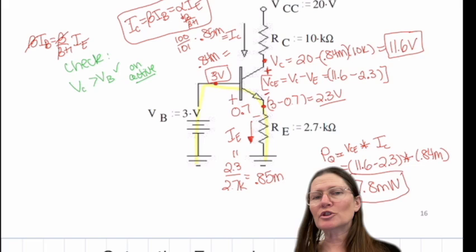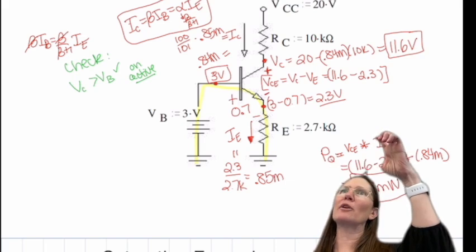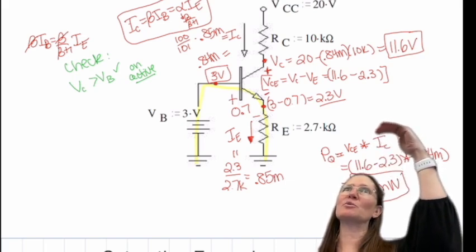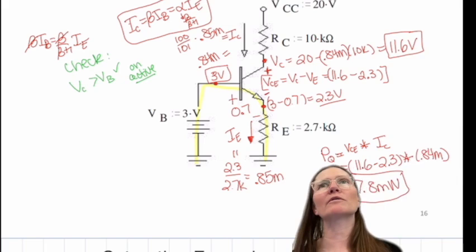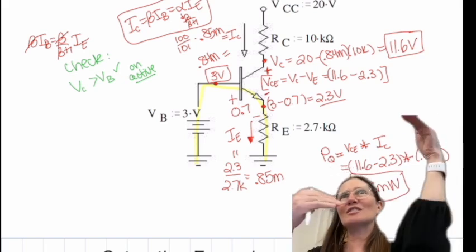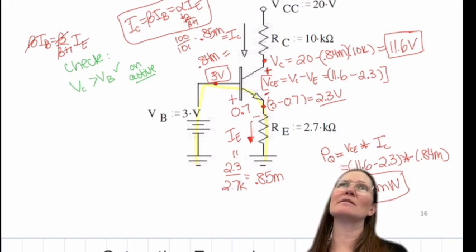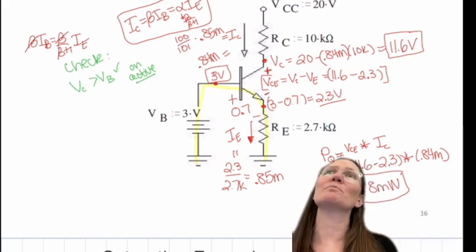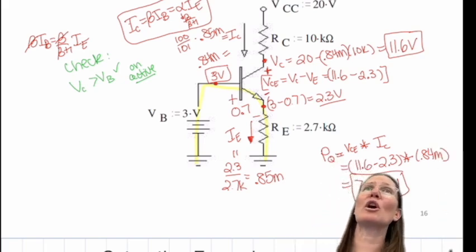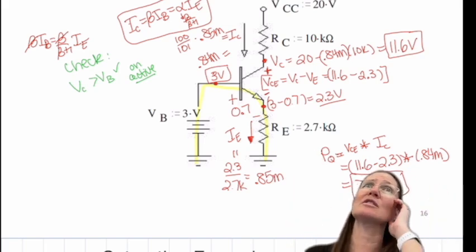So that is a voltage difference, which sometimes is hard to think about. If I have two batteries, I'm actually taking the difference between the two batteries. That's when you see that labeling like VCE, VBE. That's the difference in voltage between those two locations. It may not be an actual physical connection, and it may. It just depends. But most of the time, there'll be some element in between there. In the BJT case, you don't know what's really going on in between those two locations, but you know there is a variation in voltages at different times.